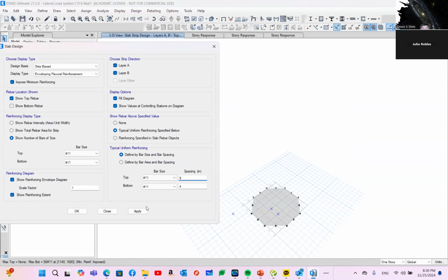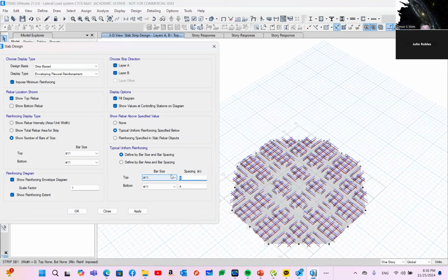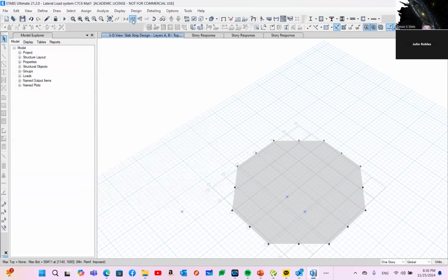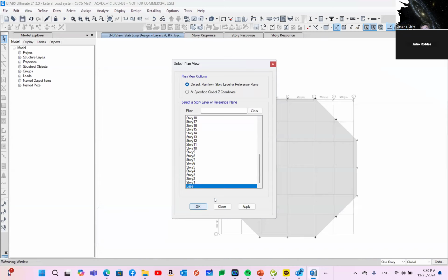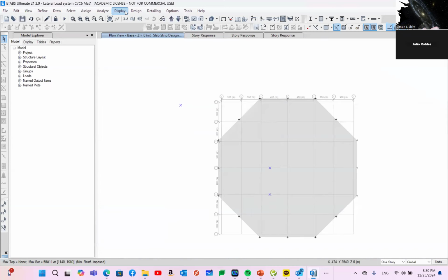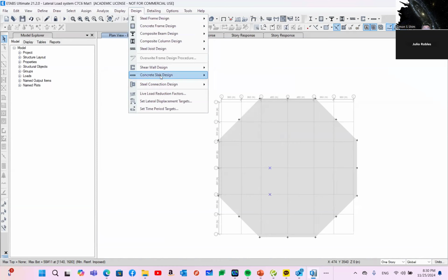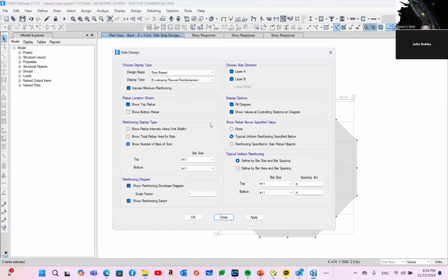If you're using 9-inch spacing, you still have to add this much rebar, but at 8-inch spacing it is gone. So you might decide on number 11 at 8-inch on center for the top bar. But for the bottom bar you need more.